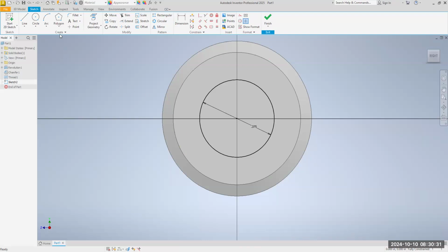I'm going to go to polygon. I want 6, but look, don't select this one. Select this one, circumscribed. Okay. And we're going to come over here and click at the center. You've got to make sure you click on that one. This one right here. See this one? There's 2 of them. Click on this one. And we're going to go up at the 12 o'clock position and it's going to snap right there. Click. Do a right click. Okay.